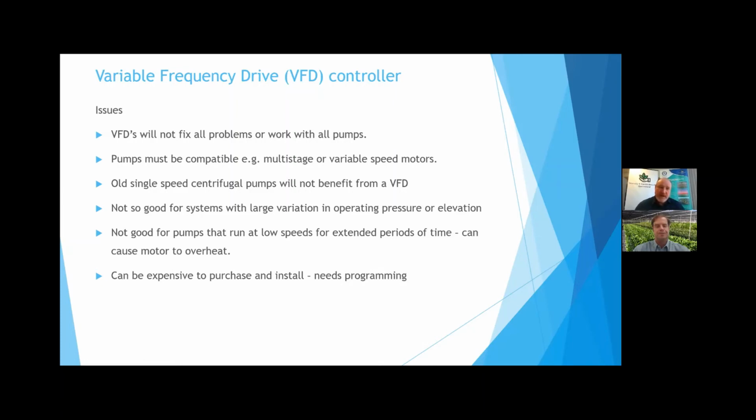They call it a variable frequency drive because the mechanism adjusts the frequency of electricity going to the pump, just like a volume knob on your stereo. So it turns down the frequency, therefore the speed of the pump drops, or you can turn it up and therefore the speed of the pump increases.